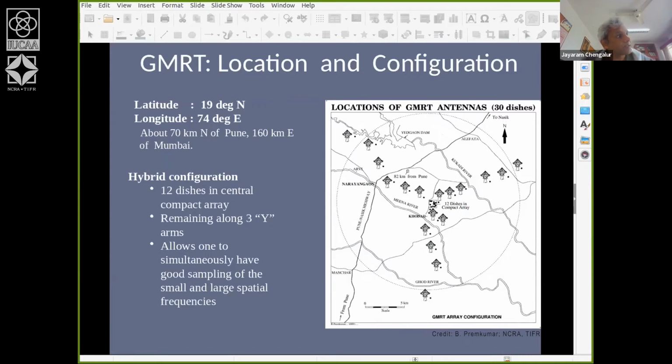It turns out, for example, that if I put my antennas on a circle, it actually gives me very nice sampling. It allows me to measure a very large number of points, and it gives me a good distribution of sampling, excepting with the following problem, that I have multiple measurements of the same visibility.